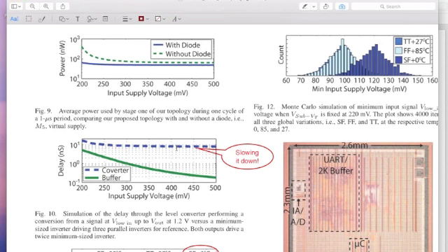So it's kind of portrayed as if it's a positive thing, but if you really look at it, it's like you have a constant delay across different voltages, so it's a good thing. But on the other hand, how have you achieved that? You have achieved that by really slowing down your level converter delay at the higher voltages. So it's not necessarily a good thing, because if I have a design which is supposed to work well across a large voltage range, here you are unnecessarily penalizing, using this particular topology, the operation at higher voltage, because this level converter is giving a large delay compared to a simple inverter. Here the delay penalty is not much at low voltages, but at high voltages I have a large delay penalty.